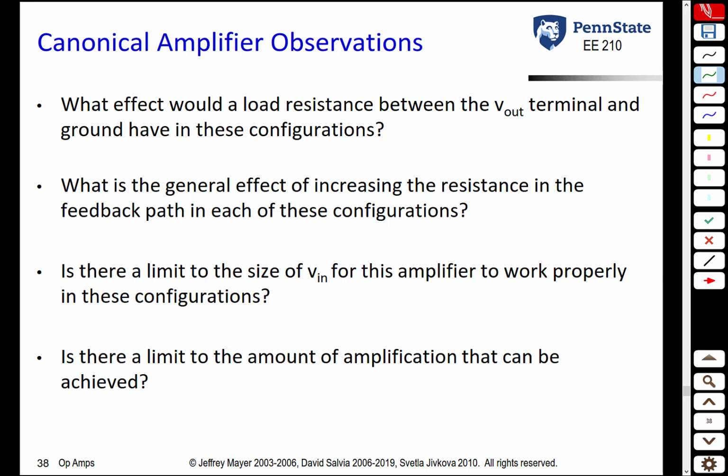As we saw in all of these, when we write the KCL equation to find the output voltage, we're not doing it at the output terminal. We're doing the equation at the inverting input terminal. So what we see is that the load resistance has no effect on Vout. There's a caveat here. It has no effect on Vout provided that the op-amp circuit is operating in its linear region and provided that the output current is less than the maximum output current that the op-amp can provide.